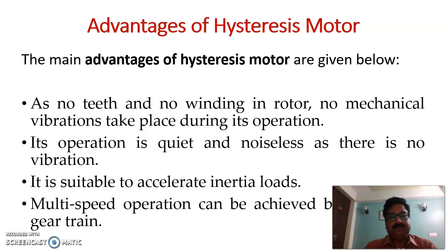Because of these properties, its operation and its construction, there are a number of advantages of the hysteresis motor. In the construction, we have seen that there are no teeth and no winding on the rotor. Because of this, mechanical vibrations are removed.